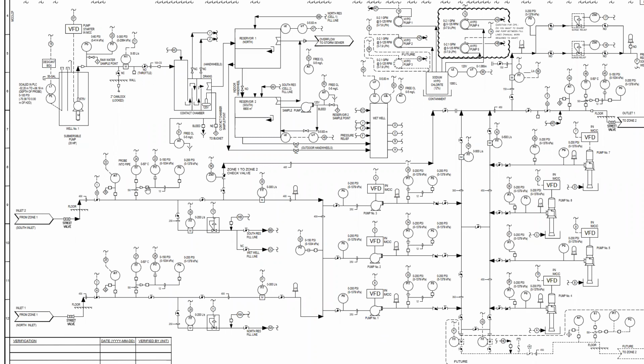Not 100% sure what that is. I believe it's just a valve, a pressure transmitter, and then this is just a pressure gauge. So the transmitter comes to the PLC, and then there's a gauge beside it to confirm that the transmitter is working or is accurate. As we move down, there's a flow that'll run into the reservoir. So we have a flow meter, and then we have a surge diaphragm valve with a hand crank on it to kind of limit the flow so we don't overfill the reservoir or fill the reservoir too quickly.